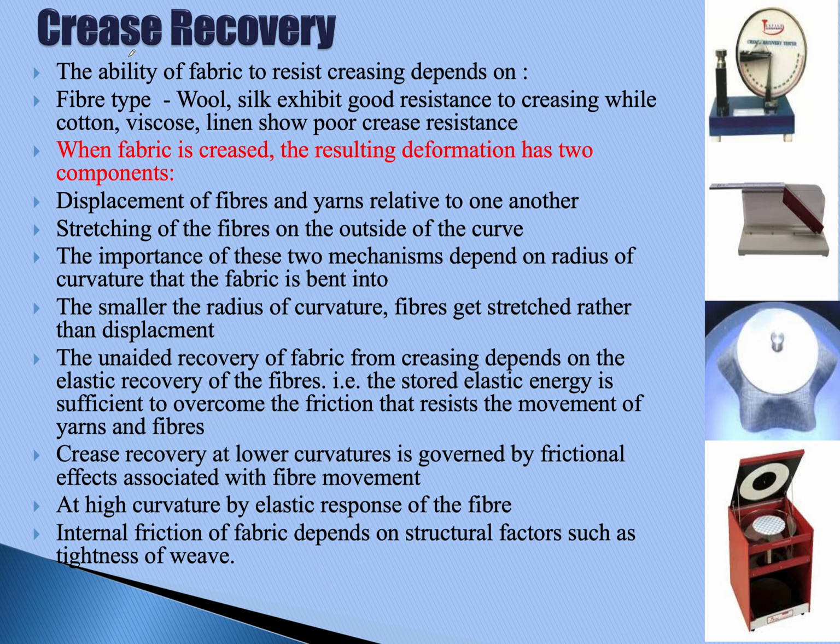The first property that we'll be discussing is crease recovery. So what is crease recovery? It is the ability of fabric to resist creasing. In normal day-to-day use, particularly garments made from cotton fabrics are subjected to maximum creasing when they are washed or even during wear, during use. How well a fabric can resist this creasing is determined by the property known as crease recovery, and it will depend on fiber type, of course.